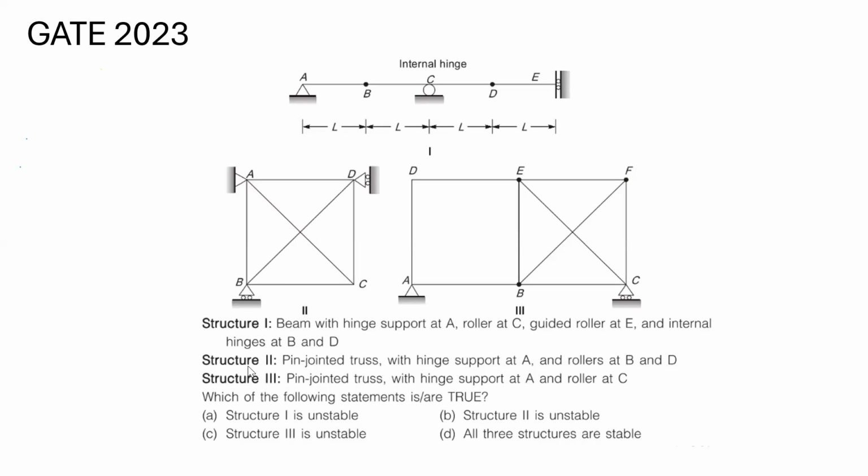But if you see the physics, what will happen? If I apply the force at C towards the left, A will act as a fulcrum and the structure is going to rotate. The structure is not stable; it is an unstable structure. Are you getting this point? Or if I pull the point C towards the right, then also the structure is going to rotate about the point A. Such rotating structures are not stable structures. So the second is unstable, sure.